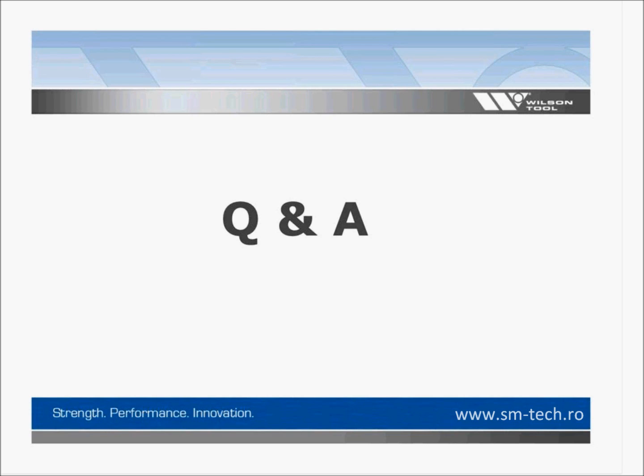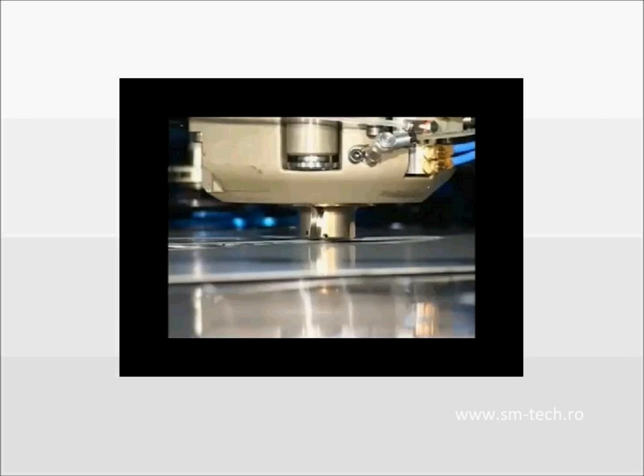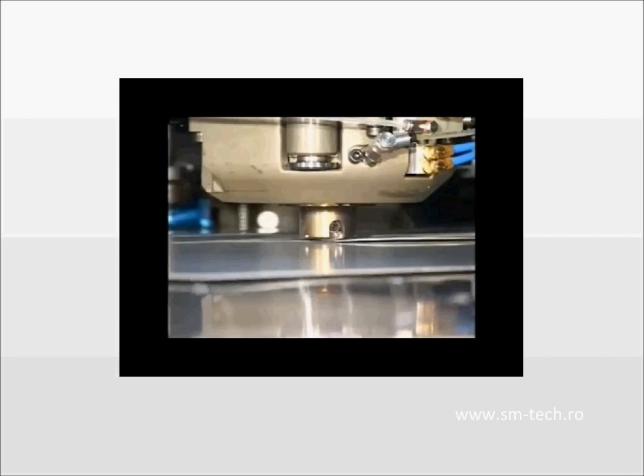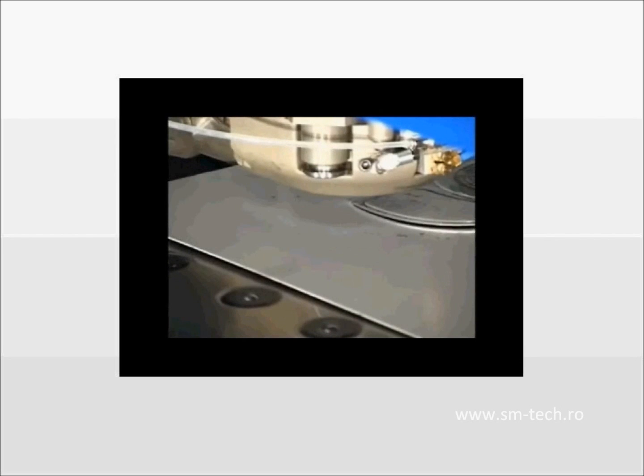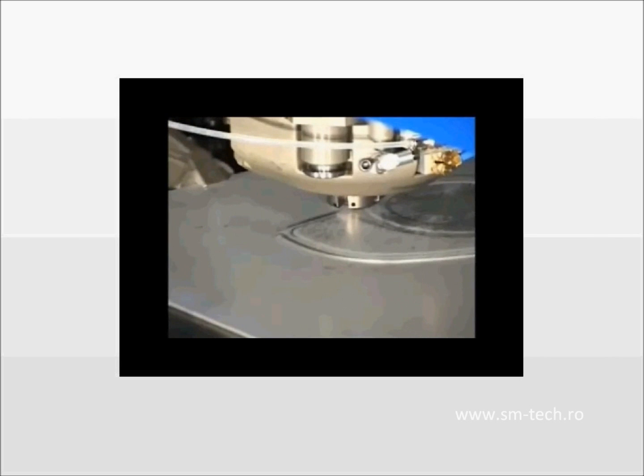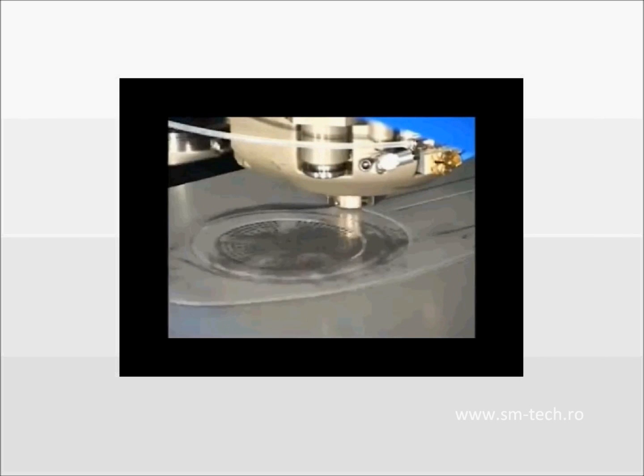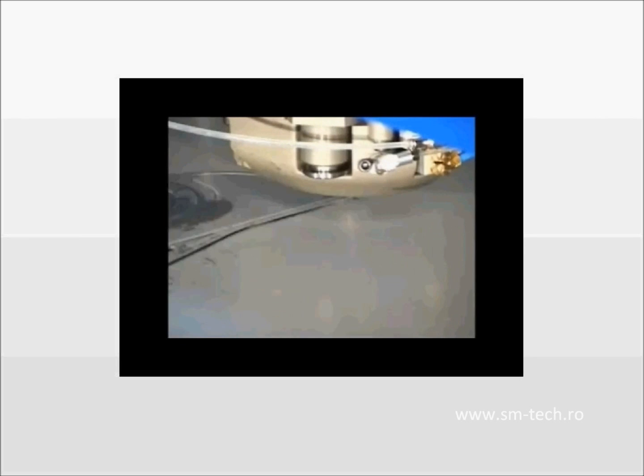Next question is, when using the rolling shear, how do you remove the pinching when it hits the material? The easy answer is to say that you really don't, because that is when that wheel comes down. Let's see if I can stop this video where you kind of see, I think we're talking about this distortion right here at the end of the cut, and now the machine's going to rotate that tool and come down and restart. So you've got a little bit of a ding in the material here. Depending on your machine, you may not have much there for options. If you see the way this machine is running, I'll run through to the end and restart this video.